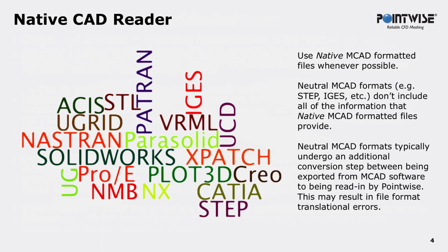In addition to IGES, STEP, and other neutral CAD formats, Pointwise supports reading the native CAD part or CAD product files from CATIA, the part or assembly files in Creo, along with several others. Chances are good that Pointwise can read the native CAD files from the software used to generate the CAD model directly, and doing so is almost always preferable to using a neutral CAD format as an intermediate step due to the additional information about the model that is included.